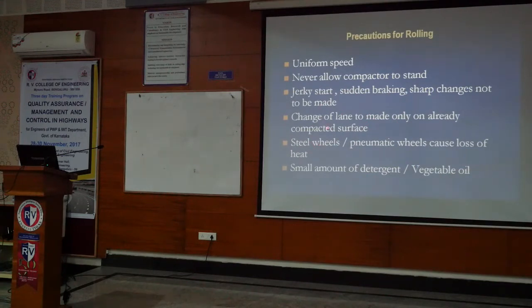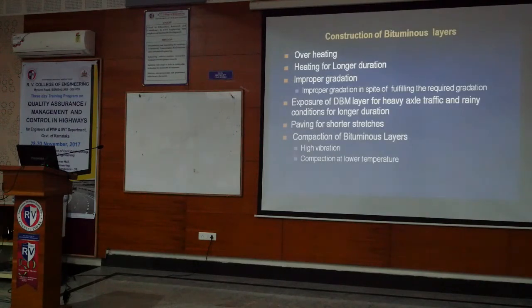Steel, we should always remember that we use asphalt compactors which have steel wheels on front and back. That means it absorbs heat of the bituminous mix. It does compaction, at the same time it absorbs the heat, which is not desirable. So we should always balance that. And these are some of the other things we should remember.